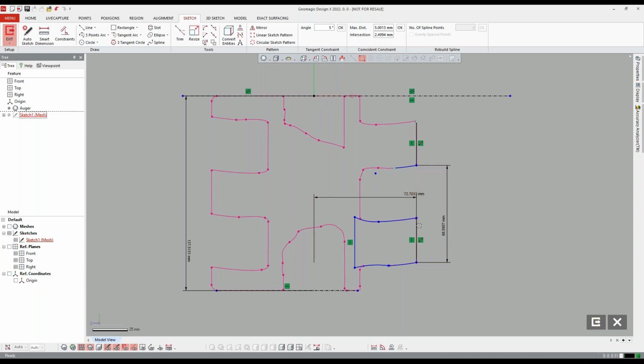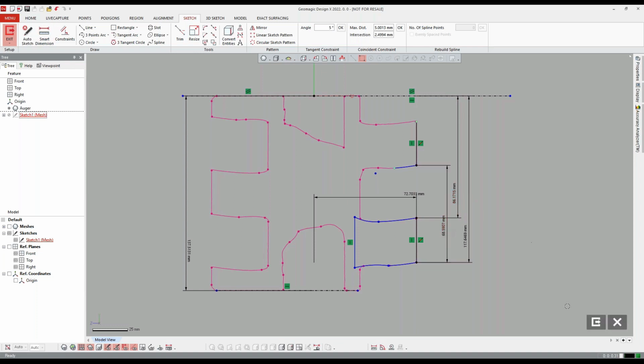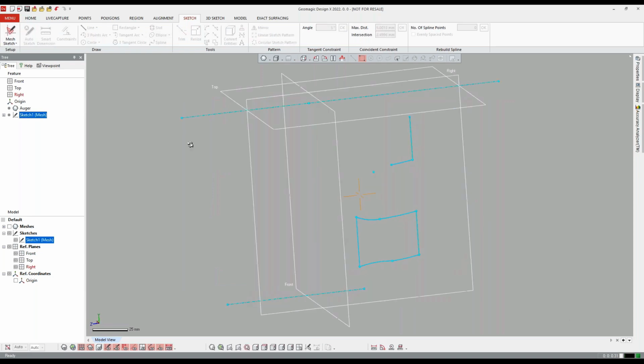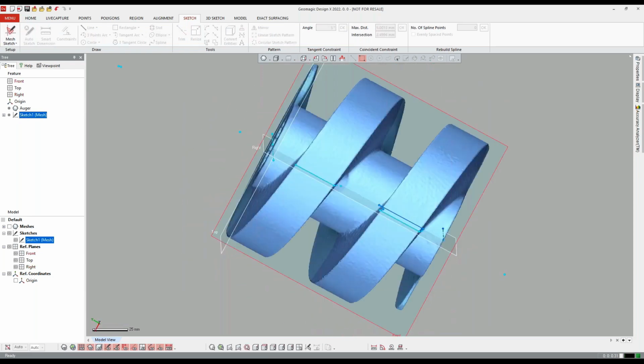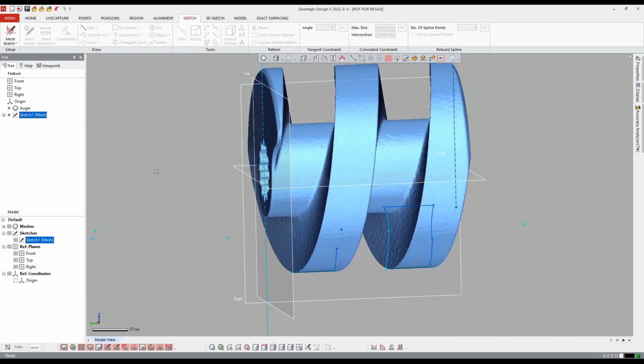So as far as start and end point of this, again, we could do the same thing off the front face. We could look at what our pitch spacing is from the teeth, but they all seem a little random. Maybe the front edge isn't, but it seems like there's just a little bit of meat everywhere. So now that we can pull that out, I'm going to put my mesh back on here, and then we're going to pick our start and end points.